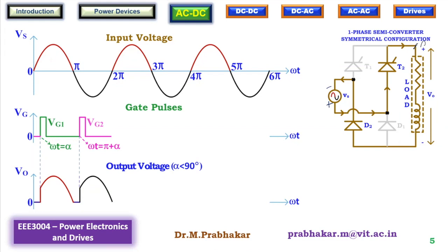I will now name these A and B for additional clarity. So B will be connected to the negative through D2. That's all. Now the current direction is going to be like this. It will start from the positive of Vs and then flow through T2, then through A and then terminal B. Then it will flow through diode D2 and then it closes. Fine. So this is the path for current.